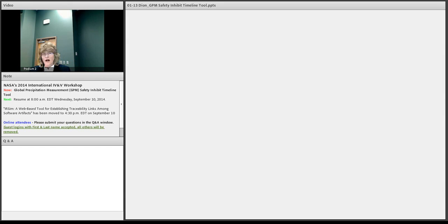The next test was functional testing, and basically that's a subset of CPT. It tests all copper paths. It looks at side A and B, but doesn't look at cross-strapping. And the time allocation for this test is much more limited than CPT. The third one is aliveness tests. This is basically to turn on all components, but only verifies a few key components like voltage and current. It also tests A and B side, but there's no cross-strapping again.